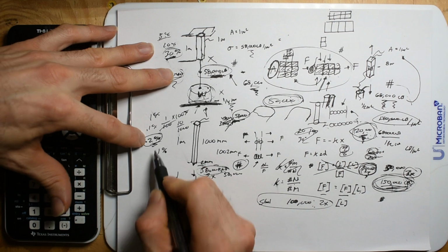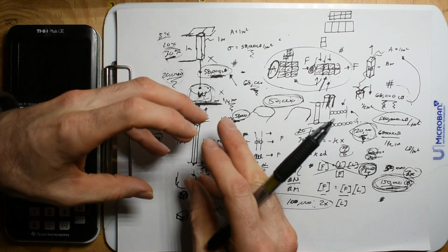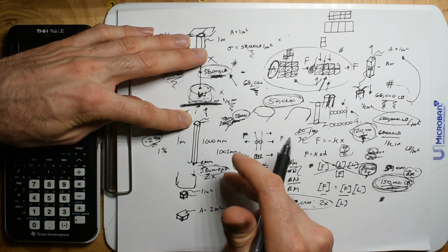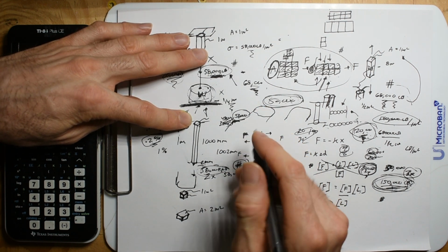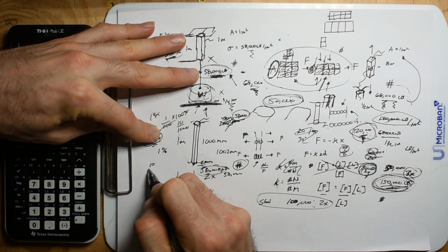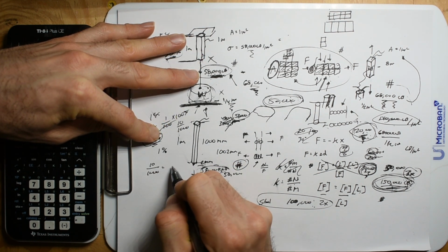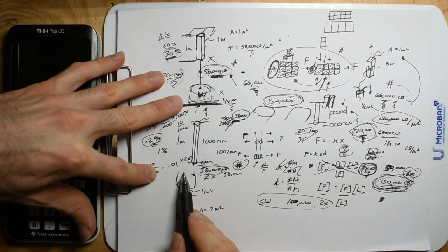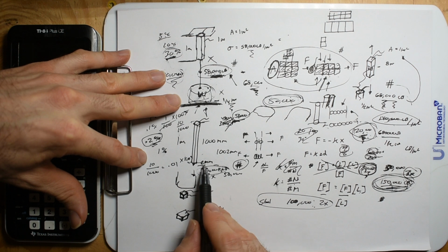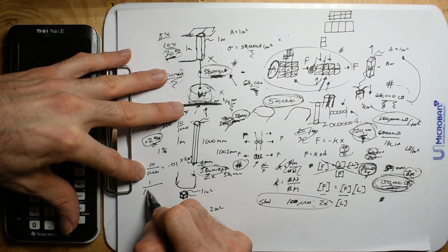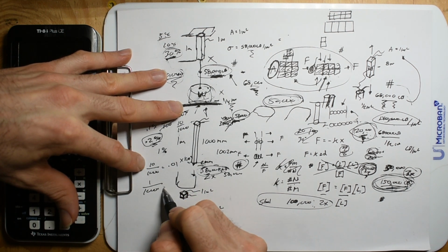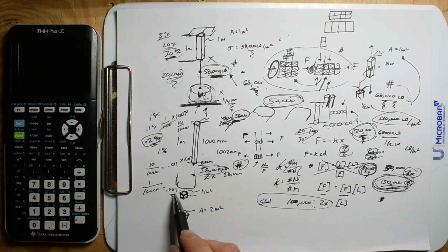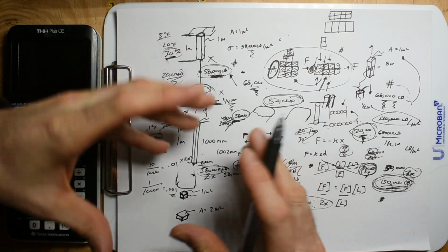We don't actually use percentages. It's just a good feel for how much things are stretching compared to their overall length. What we do use is fraction of the overall length. So if I stretch it 10 millimeters, the overall length is 1,000, that would be 0.01, and again, this is what we would multiply by 100% to get 1%. If I stretched it 1 millimeter in 1,000 millimeters, I would get 0.001. We have to work in thousandths, a fraction of this whole.